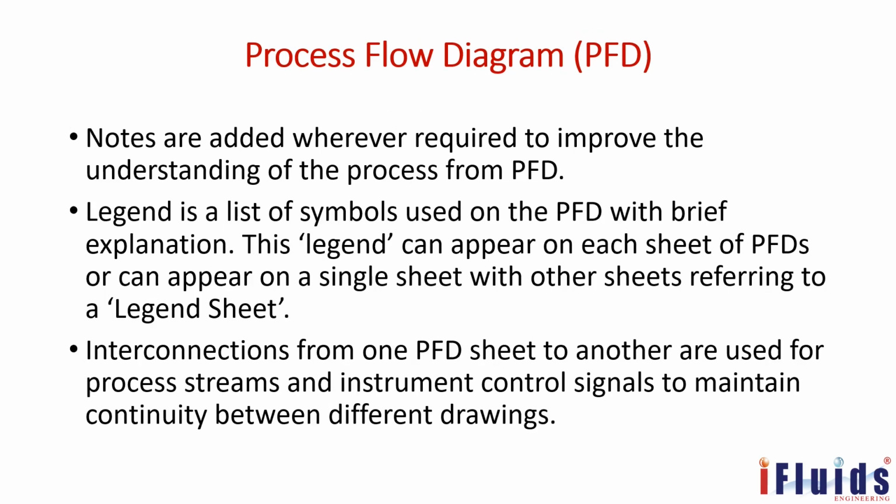Notes are added wherever required to improve the understanding of the process from the PFD. You can put a note wherever you want to explain or give more information. You can add a small note: this stream is from this vessel, this is going to that column. Like that, small notes you can put.